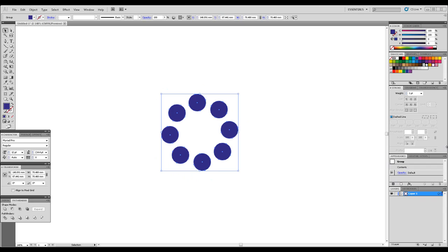The next tool worthy of note is the Free Transform tool. The Free Transform tool can be found in the Tools palette 2 down from the eraser. With the Free Transform tool selected, if we go over to our canvas and hold down Ctrl at the top middle of our shape, press the left mouse button and drag across, you'll see that we can manipulate and skew the shape.